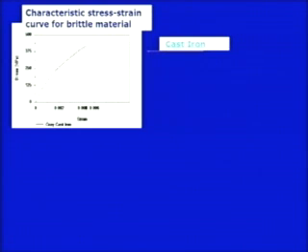If we go for the axial pull, here there is a stress-strain relationship, but it is not showing any elastic region or plastic region; there is no upper yield or lower yield limit, and no proportional limit. Straightaway as you apply the load, there is a stress component and a strain component, and up to a certain point it shows a non-linear relationship; there is no linear relationship between stress and strain. Then it goes for fracture. At the point of fracture or rupture, we have a zigzag or irregular shape. In ductile material we have a cup and cone structure, while for brittle material or cast iron we have the irregular shape.